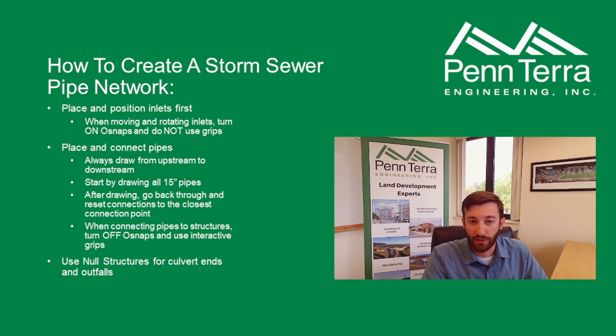The next step I do is place and connect all of the pipes. This first bullet point is really important. You always want to draw your pipes from upstream to downstream. If you don't, the storm charts will not work, and you're going to end up having to delete pipes and put them back in the right direction, or grip edit and flip pipes around to make it work. So that's always really important, and that's some of the reason why I put all of the inlets in first, so it makes it easier down the road to just connect the pipes from high to low.